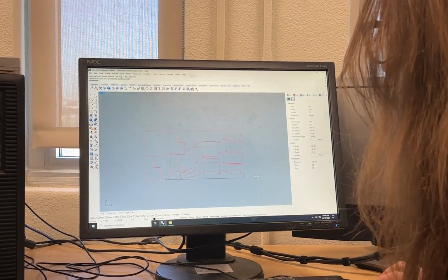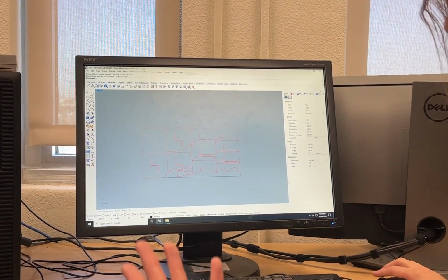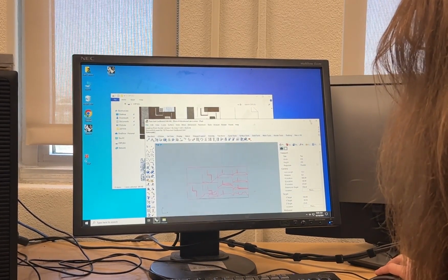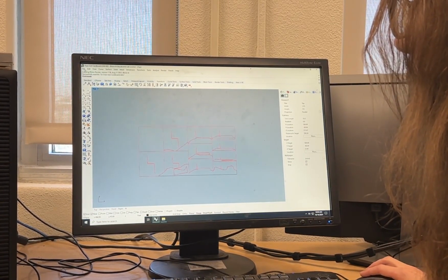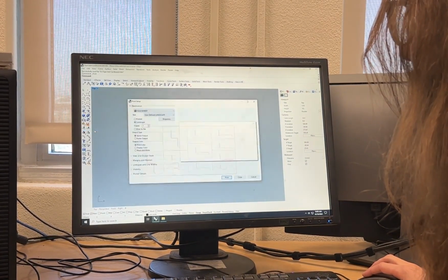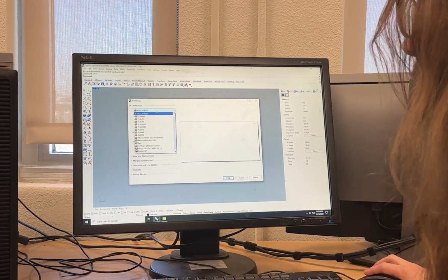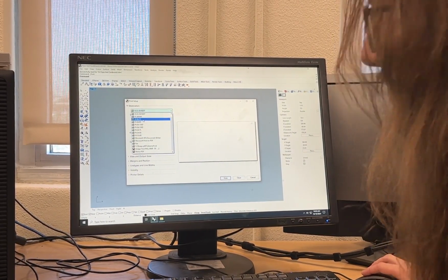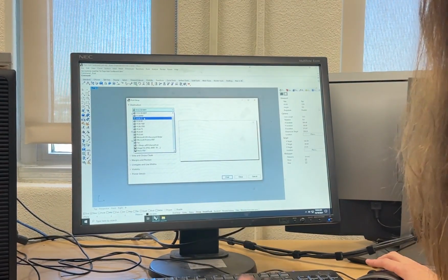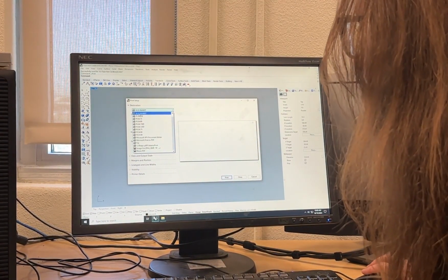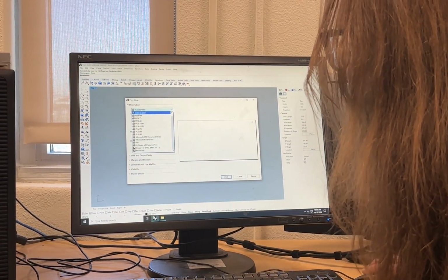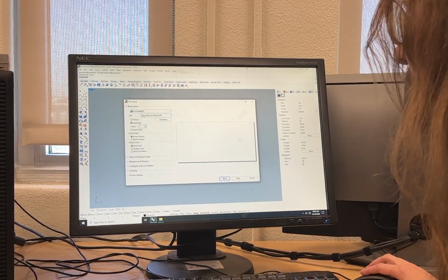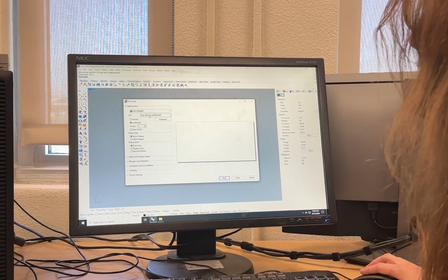Anyway, so all we have to do is basically press print. So we'll go to File. Let's make that a little bigger. File, Print. By default, it is the laser cutter that you need. To be fair, I think these are all previous versions of this laser cutter that have had to be set up over and over again. Just make sure you're on VLS3.50, and again, it's usually the default, but just in case you need to see it, at least it's being recorded.